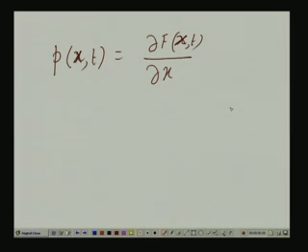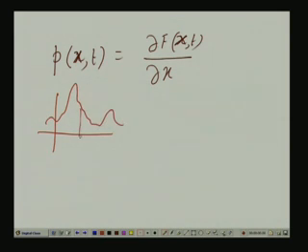Now we can make it two random variables, that is, we can define joint distribution and joint density. We can consider a particular sample function, say at t1 and t2, and fix t1 and t2. So, this x of t1 and x of t2, they are two random variables, because depending on a particular waveform or particular outcome, they take some values. Next time the waveform changes, they take other values. So, they are random and they are jointly random, they are varying jointly hand in hand. That means we can define in an analogous way their joint distribution and joint density functions.